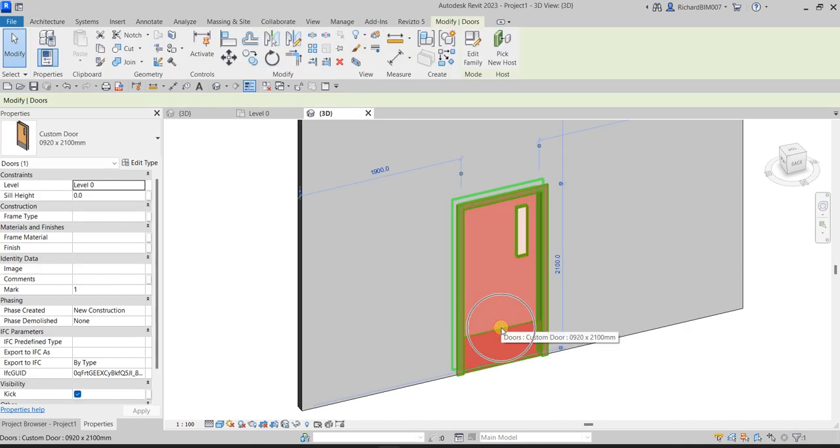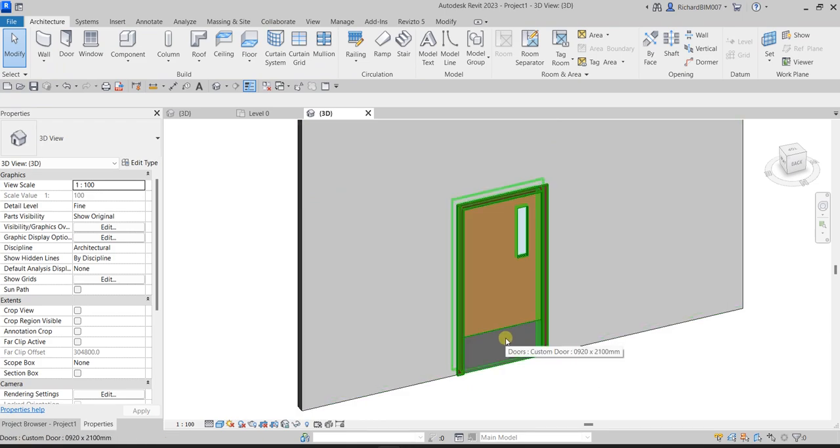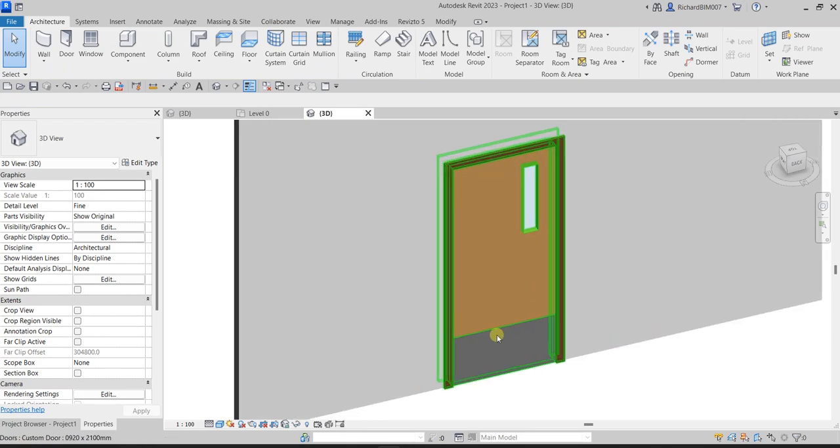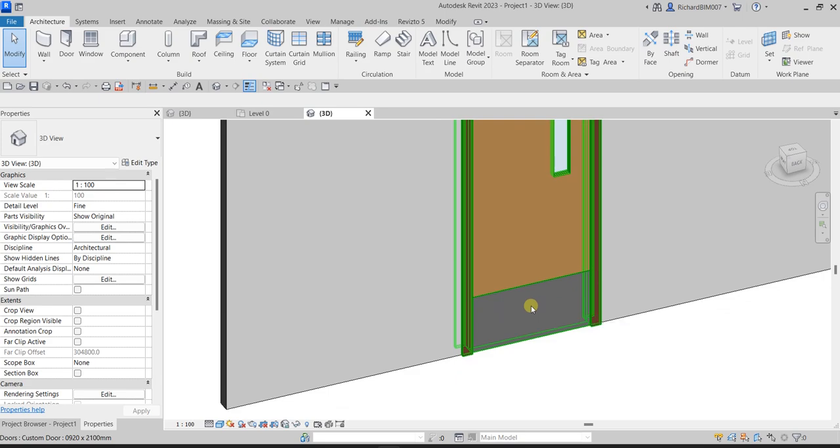So if I click this, since our kick parameter, we selected instance, right? So you can see it here on the instance properties. So you have an option to make it visible and invisible, right? There you go. So I click again, kick, apply. So this is instance parameters or instance properties. That's why you are able to see the kick, because our kick parameter, we put that on the instance. So the height, we put that in the type, right?